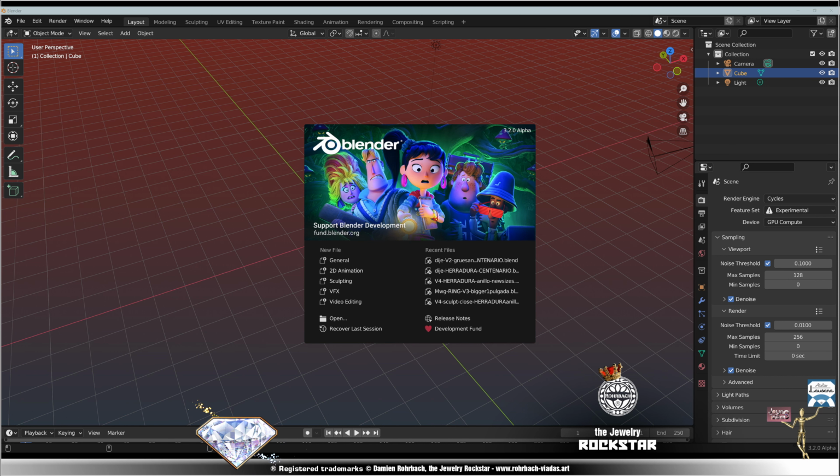So we can't, because generally the clamp overlap is turned on to avoid a destructive bevel depending on the distances you have, because most of the time, if you have sharp tips like these, sharp corners, in fact, the bevel can't be made by the software, by Blender, by mathematics, also because the borders are going to overlap themselves and destroy the mesh.